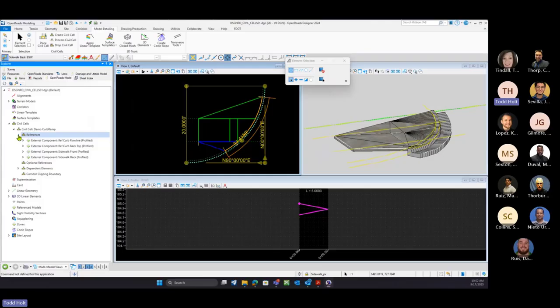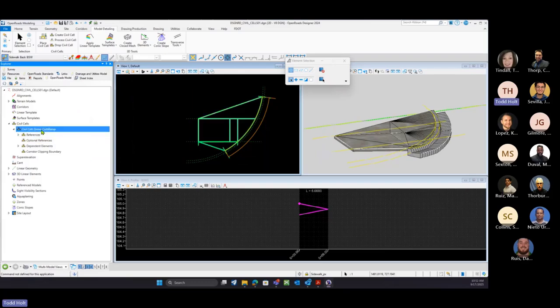Everything within the civil cell is going to be in the dependent elements. Before we get to that dependent elements, another thing that'll come is I'll select on the name and then right click on it. We see this as place civil cell under that general category, or if we go to the properties of it, this is going to be valid for placement.